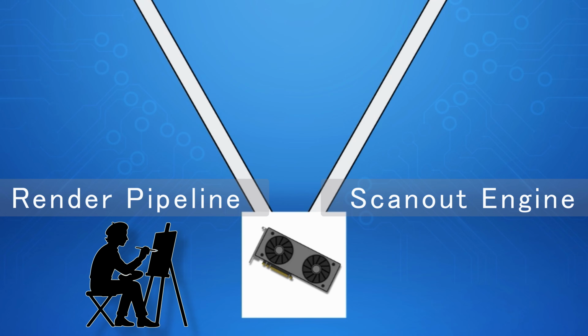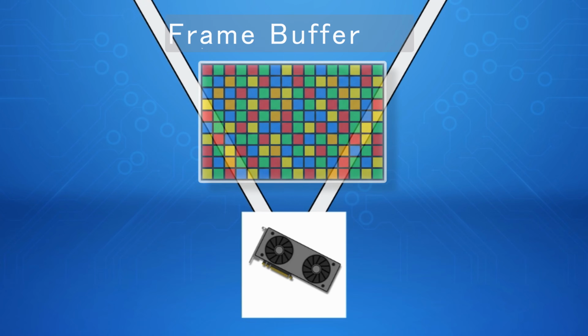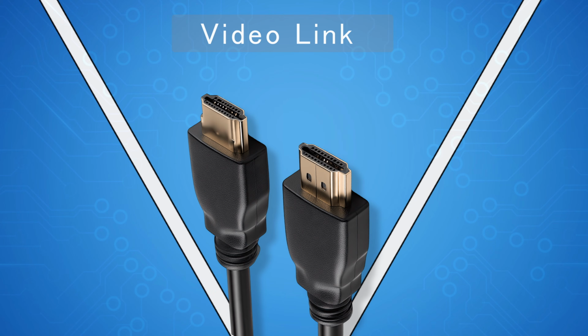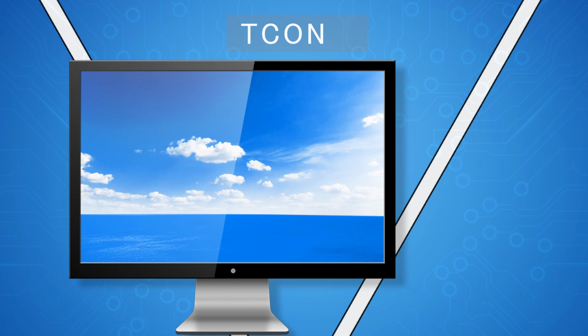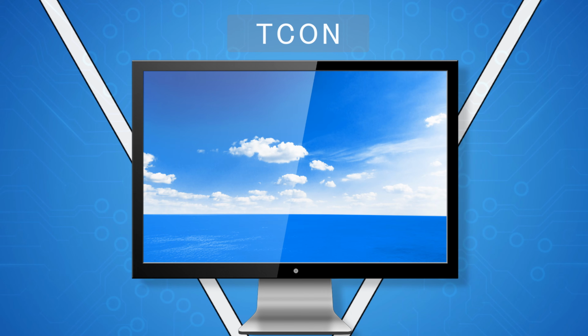Second, you have the scanout engine. This is the delivery truck. This part of the GPU doesn't care how the image was made. Its only job is to read the finished painting at a fixed schedule and ship it out the door. That finished painting it reads is called the frame buffer. This is literally just a block of VRAM that holds the final color value for every single pixel on your screen. For a 1080p display, that's over 2 million pixels. For 4K, it's over 8 million. And finally, you have the video link, your HDMI or DisplayPort cable, and your monitor's T-Con, or timing controller. This is the final delivery and assembly line, turning that data stream back into light.